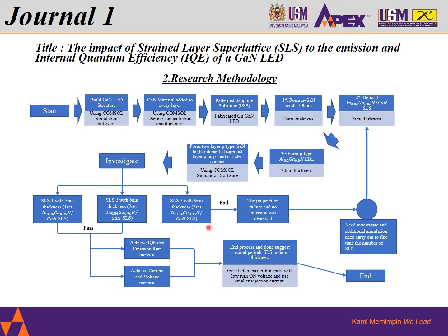In the investigation of SLS with 9 nanometer thickness, it showed that the PN junction failed and no emission was observed. Additional simulation needs to be carried out to fine-tune the number of SLS to get a better result. And this is journal one.